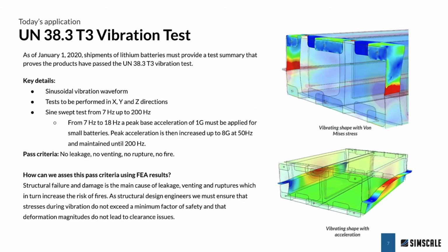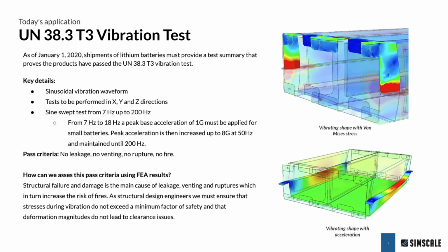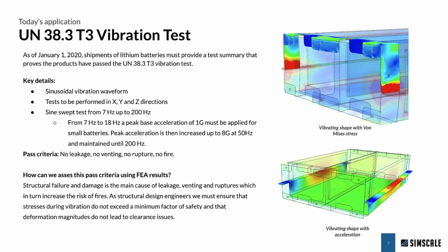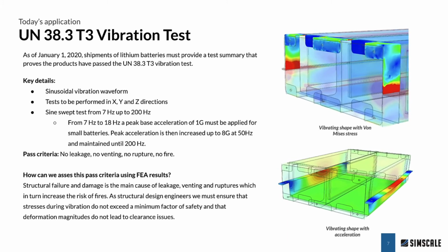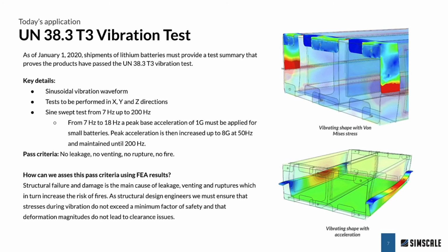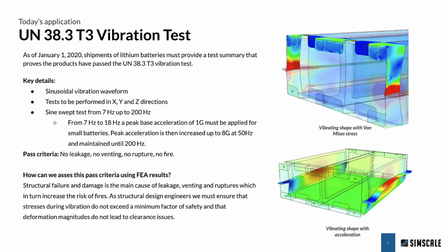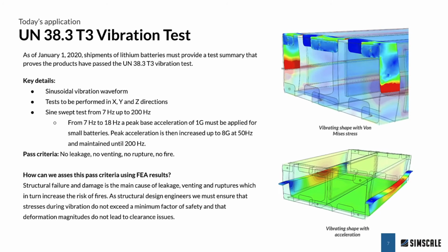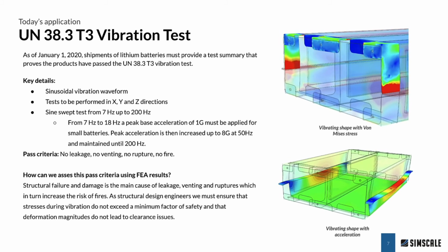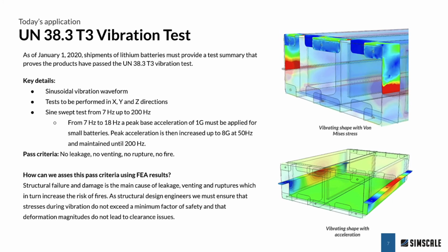This standard has been valid since January 2020, and it demands that any shipment of lithium batteries provide proof that they've passed the 38.3 T3 vibration test. So what does this test entail? During the test, cells and batteries are firmly secured to the platform of a vibration machine.